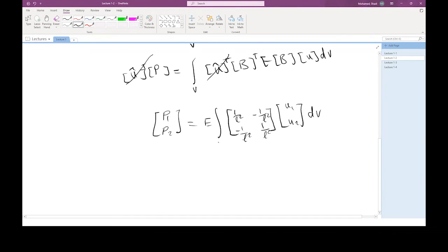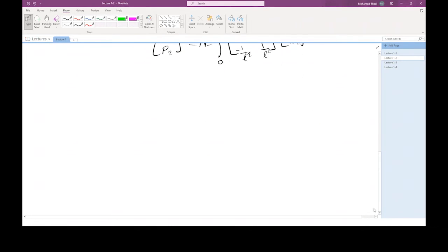And replace it with an integration over the length, so between 0 and L. And this one here will be an integration over the length instead of an integration over the volume if I take A as the cross-section and put it here. So I have A multiplied with the elasticity modulus, and then the integral of these quantities. Now, again, this L squared is a constant, so I'm just going to take it outside. Just going to write it down here.